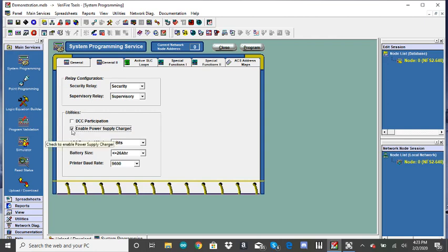But if you don't have batteries and you want to do the battery hack, you need to disable this first. There's no way to disable this through the panel's display. You're going to get a charger fail if you try to do the battery hack on a Notifier panel without turning this off. If you have over 26 amp hours, you need to set it for greater than 26 amp hour because that lets the panel know that it can allow a little bit more current to go through the charging cable for the batteries. ACS terminal mode, keep that on 7 bits. You won't need 8 bits for really anything.